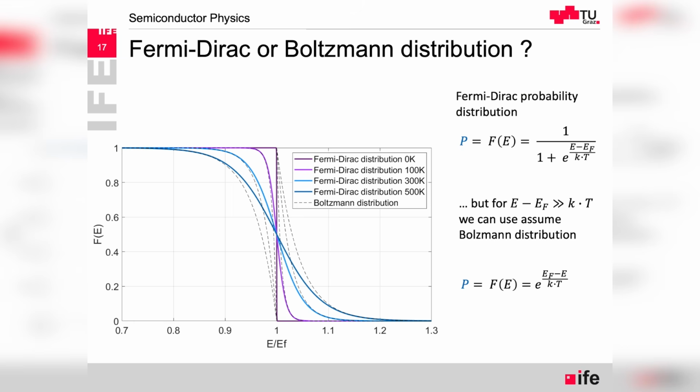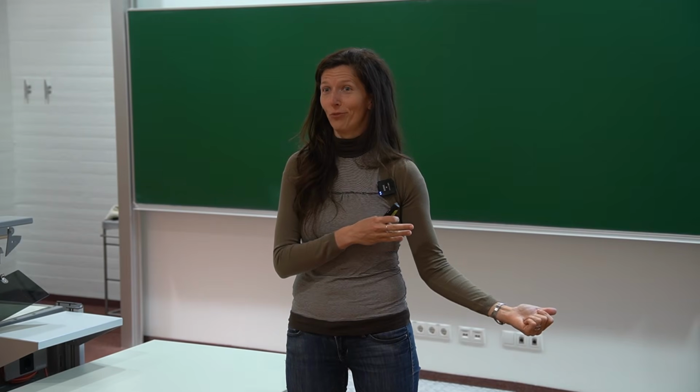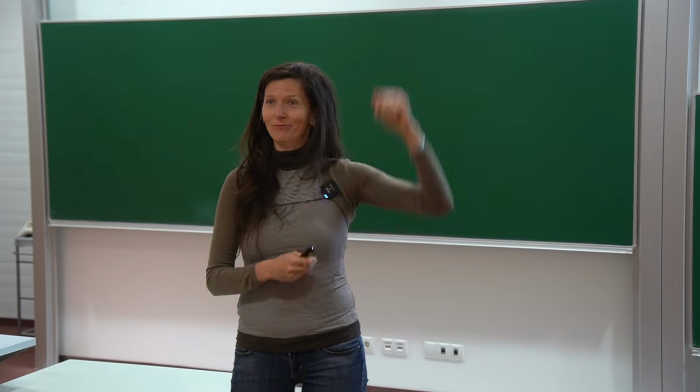What I always like is the simplifications, and I think everybody appreciates that. Usually when you read about semiconductor devices, where we will be talking about the Fermi energy, it's still important, but we don't operate with this probability model, which is the Fermi-Dirac distribution, because it describes quite precisely what happens in the middle of the energy gap, but we really care about what's below the top of the valence band and what's above the bottom of the conduction band.